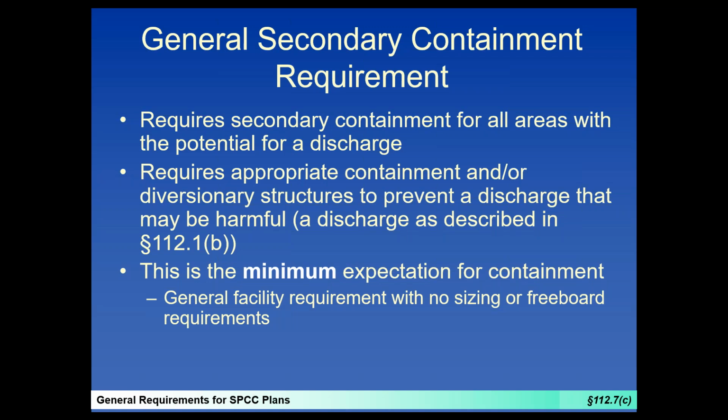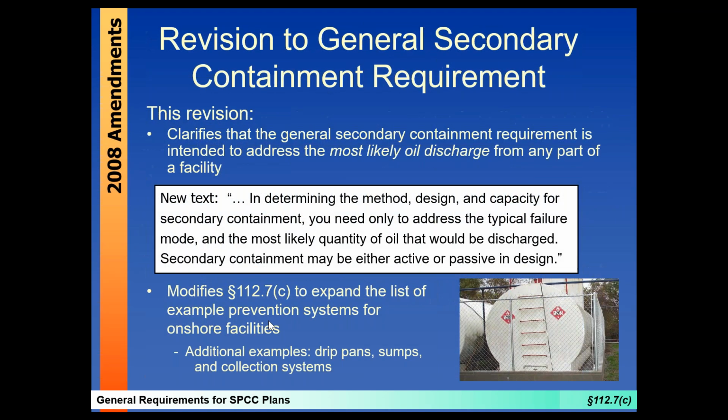And what that says, very simply, is you must have a form of containment. And when determining the size of that containment, you need to only address the typical failure mode or the most likely quantity of discharges of oil. It can be active or passive in design.